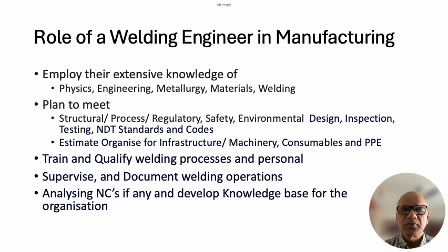and accordingly additional welding procedures, if required, are qualified, and then we need to qualify the personnel depending upon the type of joint, depending upon the position in which we expect that particular joint, or the number of joints in that equipment, the environment in which he is going to weld it, the machines on which he is going to operate. So welders and welding operators will get qualified.